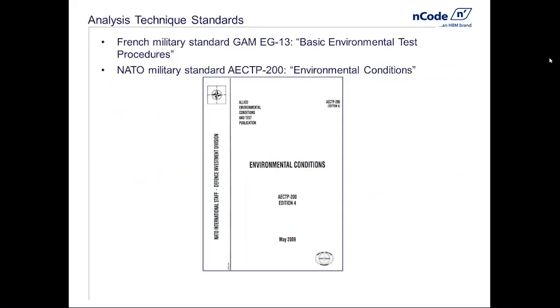The techniques we're going to talk about today come from 2 military standards, French military standard GAM EG13 and a NATO military standard AECTP 200. You can look this up and you'll find in there they talk about things like the shock response spectrum and the fatigue damage spectrum. Now we've taken these concepts and coded them up inside the nCode software. So from this point forward, we can focus on using the concepts of fatigue damage and equivalence and shock and frequency spectra as engineers, and we don't necessarily have to get into the dirty math behind the scenes.